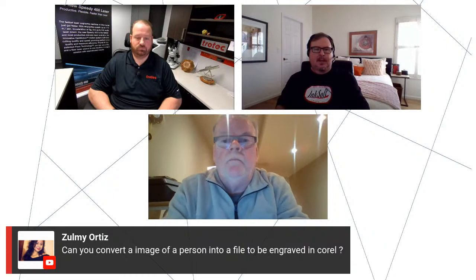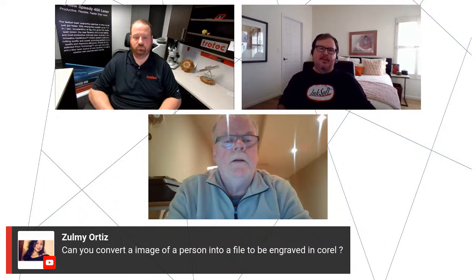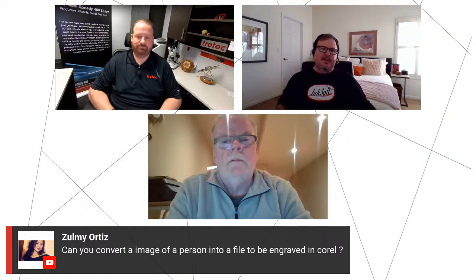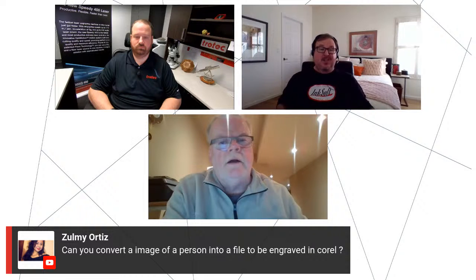Yeah, Zumi, you should be using your convert to halftone function in Smart Designer to do all that. You can adjust all the dot angles, the offset of the dots, the size of the dot, the spacing, remove contrast, bump things up. That halftone feature, I'll do you a favor. I will showcase that in a great deal of detail on the March 1st webcast, so you have a clear understanding of how to do it. It's a pretty neat function, and you can do etching.